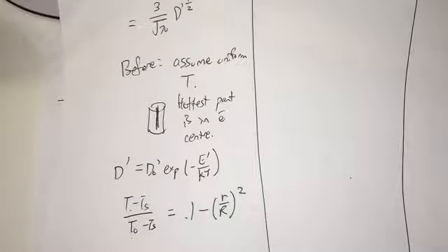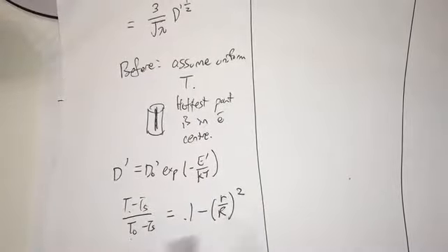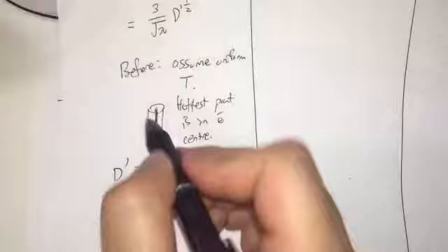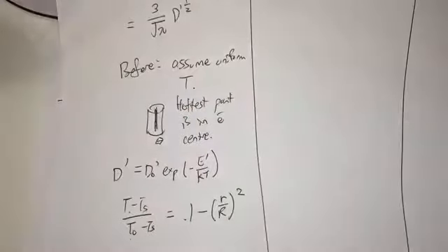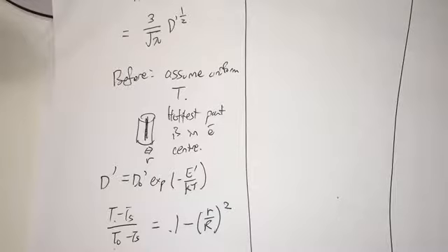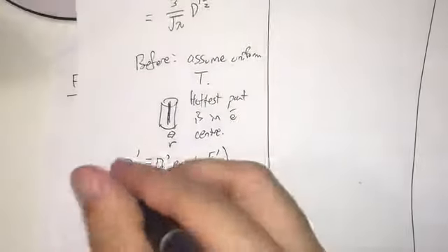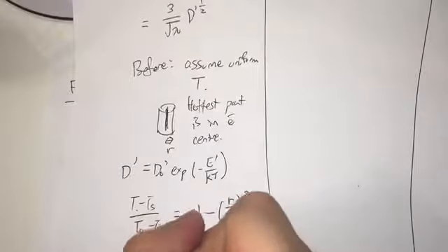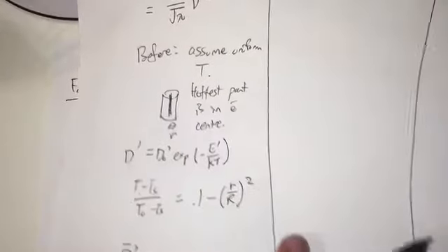So this is a typical fuel pellet temperature distribution. This R is for the cylinder. This is not to be confused with A, which is the radius of the sphere. So if we were to take into account all this temperature variation and repeat the analysis, we can obtain some average diffusion coefficient called D bar prime. Okay, so D bar prime is here,